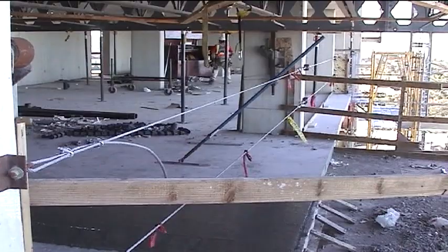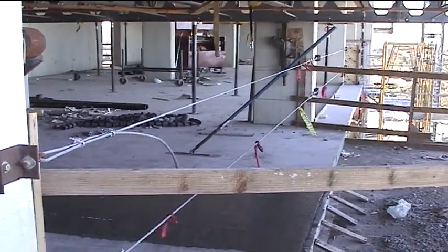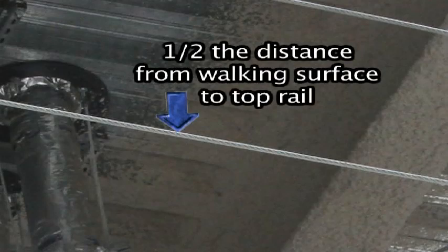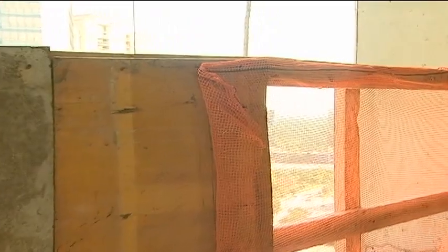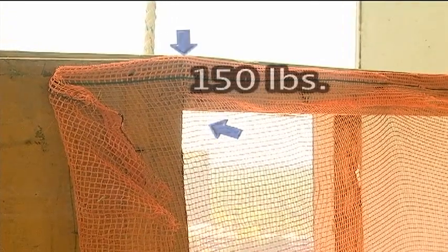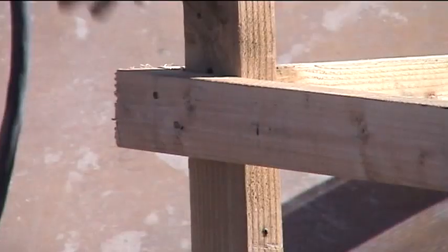If cable is used as a top rail, it must be flagged at not more than 6 feet intervals with a high visibility material. The mid-rail must be 1/2 the distance from the walking surface to the top of the top rail and be at least 1/4 inch thick. Intermediate members, mid-rails, and screens must be able to withstand 150 pounds of pressure in any outward or downward direction.